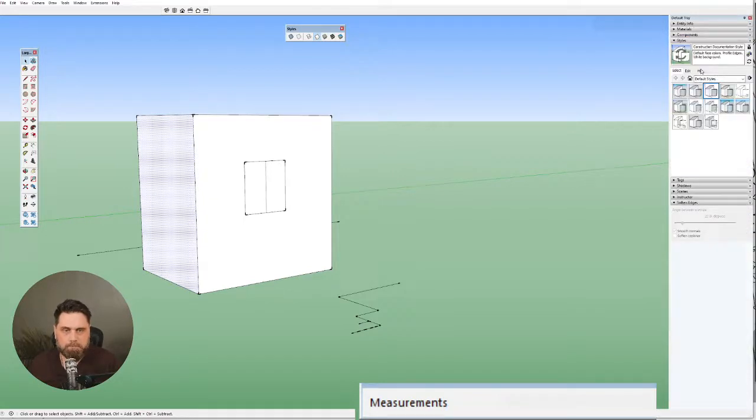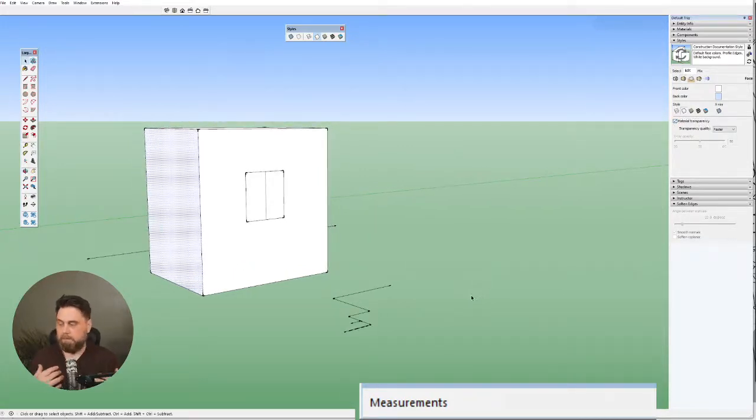Okay, so that was in our edit face settings. There's an option down here to turn on and off material transparency as well. So this will get rid of any transparency that was in the scene if we wanted to turn that off. That includes things like PNG images that actually have a transparent background, so they're cut out, for maybe people or leaves, things like that, where we'll use transparency. You can turn that off there.